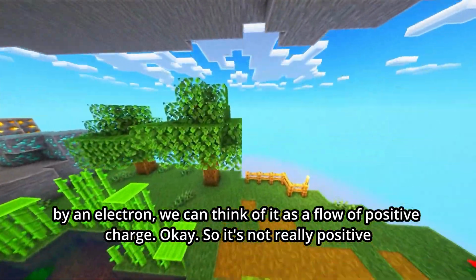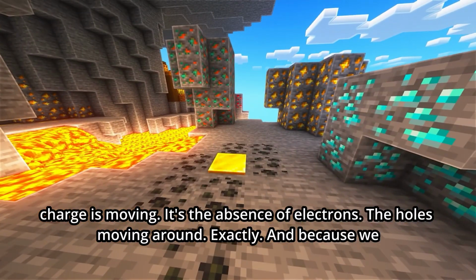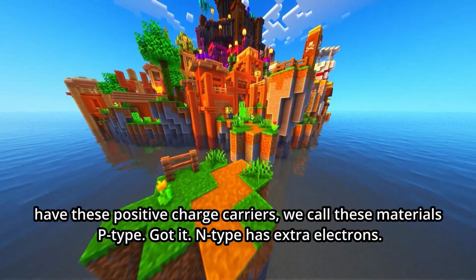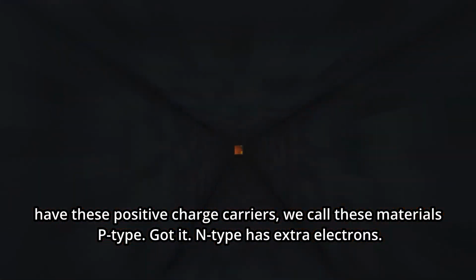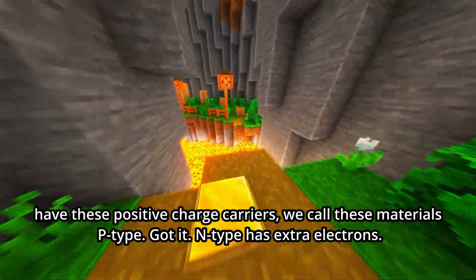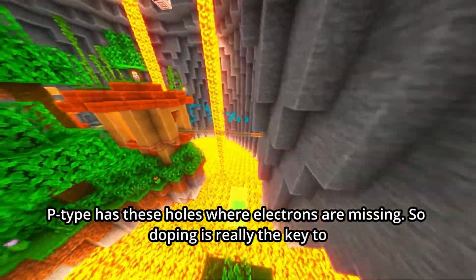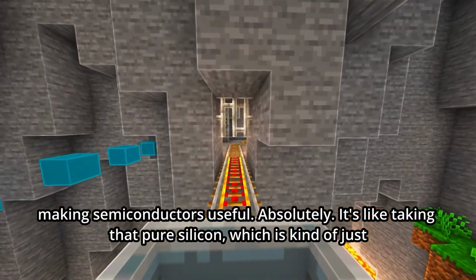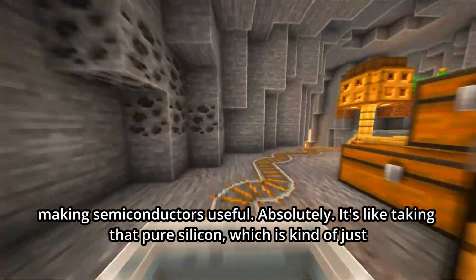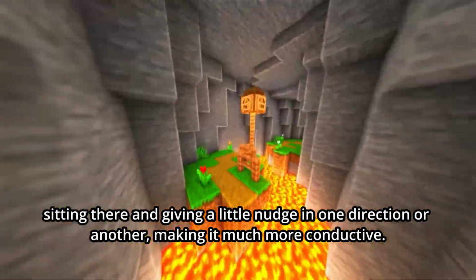Okay, so it's not really positive charges moving, it's the absence of electrons, the holes moving around. Exactly. And because we have these positive charge carriers, we call these materials p-type. Got it. N-type has extra electrons. P-type has these holes where electrons are missing. So doping is really the key to making semiconductors useful. Absolutely. It's like taking that pure silicon, which is kind of just sitting there, and giving it a little nudge in one direction or another, making it much more conductive.